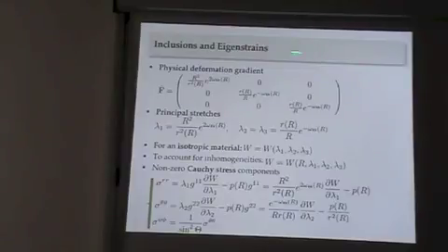So, again, classic. The non-zero Cauchy stress components would look like this. So, dW d lambda 1 could be anything. It would be mu lambda 1 in the case of neo-Hookean solids. And pressure is unknown because of the internal constraint, of course, right? So the only unknown thing here is really pressure, because kinematics I have from incompressibility and everything else.